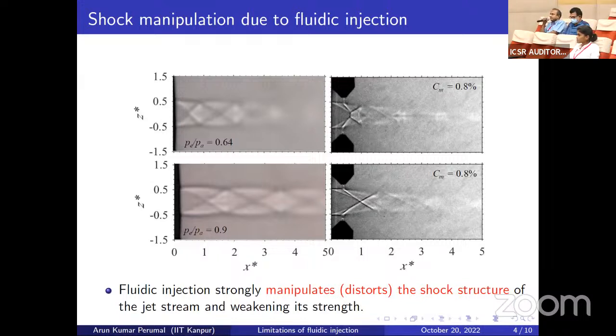Yeah, but we have looked into it. We did some measurements, one without injections. Without injections means there was no flow, but the injectors were there. So the solid object was there. But what experiments we did was with no flow, but the solid protrusions were there, just to see whether the solid protrusion is going to interfere with the shear layer and make any changes. The location where we placed it, we made sure that it is not actually interfering with the shear layer. We took the pressure data and cross-checked those things.